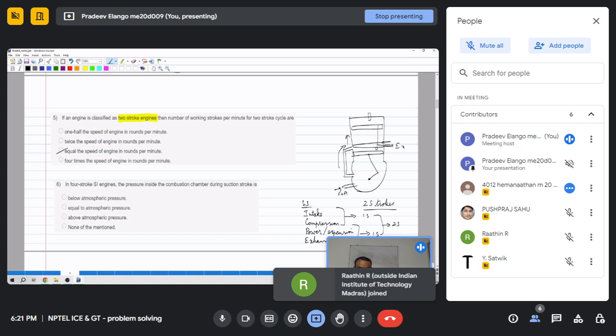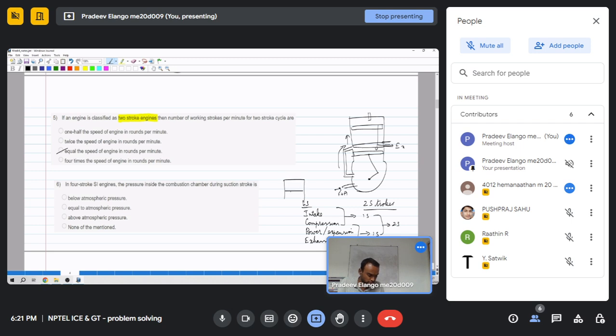No, only in a turbocharged engine will you have intake manifold pressure higher than atmospheric pressure, and then during the intake stroke you will have pressure more than the atmosphere. But otherwise, in case of a general engine, when the piston is moving down, air from the intake manifold has to enter inside, and because the piston is moving down it will create a partial vacuum.